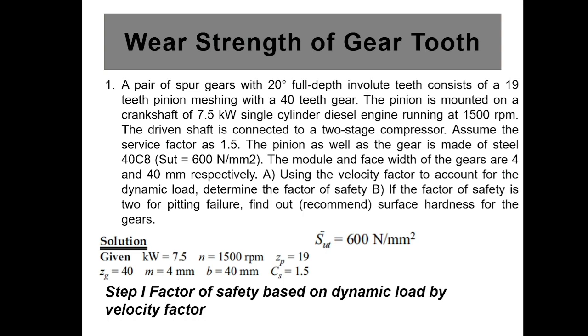So why are we designing on the wear? Because of continual rotation, there is pitting. Pitting means there are some scratches, or some material is removed from the teeth, so failure can occur in wear as well.